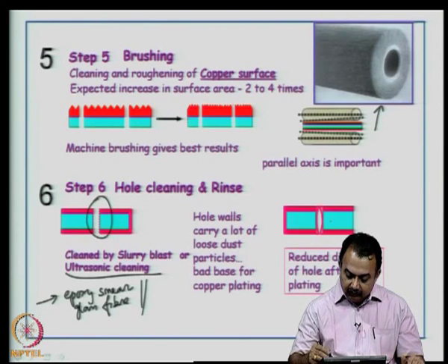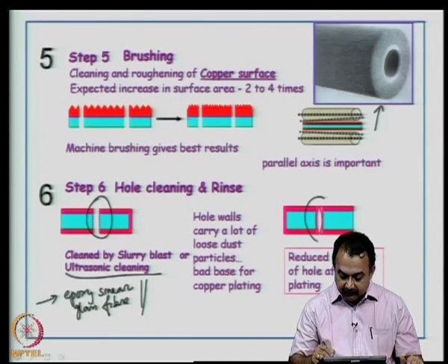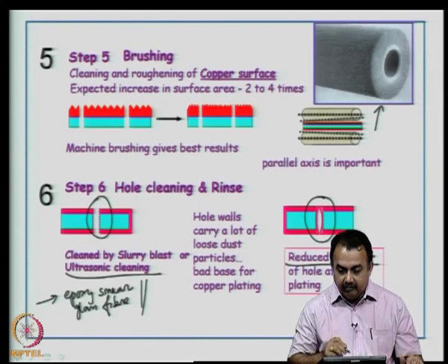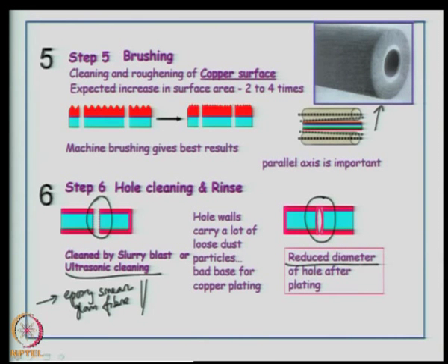Therefore, if you do not clean up, as I said, you will get a reduced diameter of the hole after plating, because for example, if you have drilled let us say a 0.6 mm hole, and if you have not cleaned it, these debris and fibers etc. after plating will reduce the diameter to let us say 0.5 mm, and when you insert a component here later, you will see that the component is not fitting into the through hole wall.